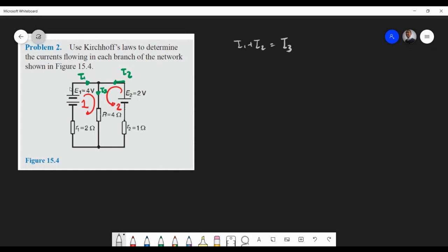So how we take Kirchhoff's, we're going to look at our voltage laws now. That is the first thing. We say the first voltage, which is the EMF, goes around, and then we collect resistors as we move along here. So we know that E1 is 4. And as we go here, in fact it's I3 going through this, so that's I3 times 4, plus as we go around here, this will now be I1 solely in this branch over here.